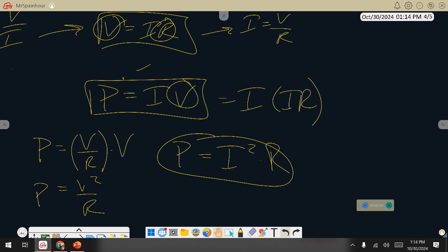Let's start off with the easy thing. What variable should you be looking at here? I said I want triple power, and I'm going to use a battery that's twice as big. What are the only two things you can control? Resistance and voltage. Well, I already told you the voltage is going to double, so what's your only other way of changing these numbers then? Changing the resistance. So you should be looking at what effect this has on resistance in order to triple power, make the voltage twice as big.